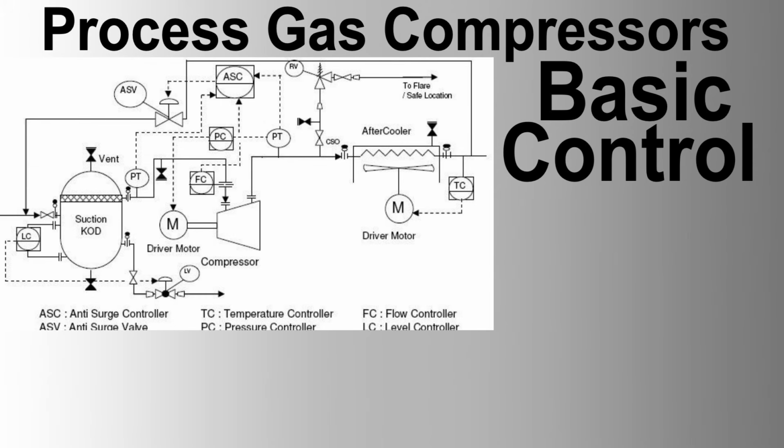2. High-pressure HP gas compressor. Function: this compressor takes gas from the LP and MP stages after being compressed to a higher pressure and further increases the pressure to a level suitable for gas injection or export. VFD integration: VFDs ensure that the compressor operates efficiently at varying loads and process conditions.